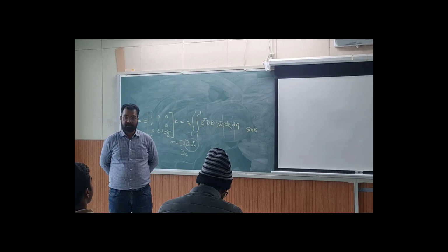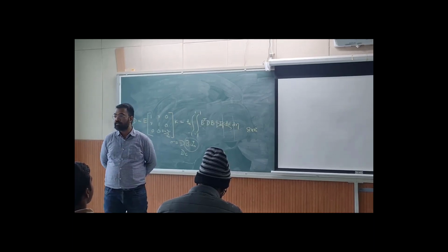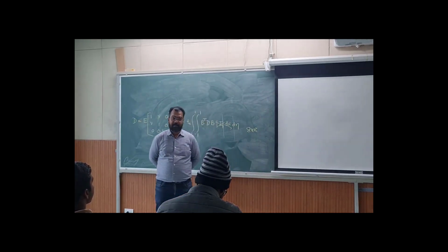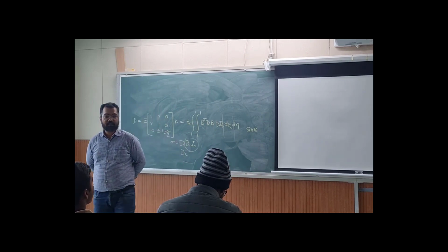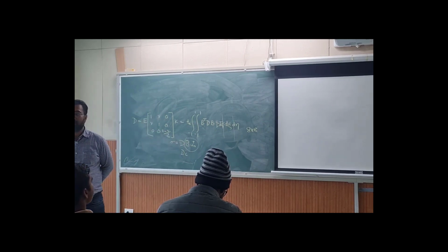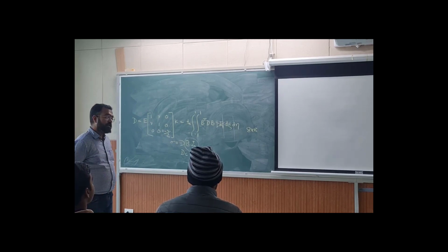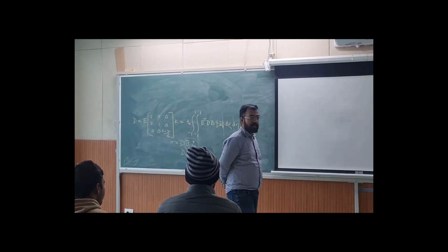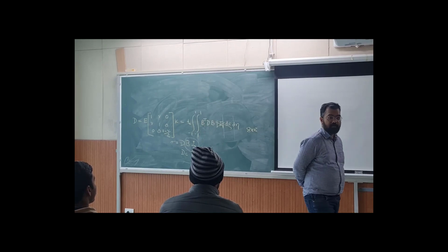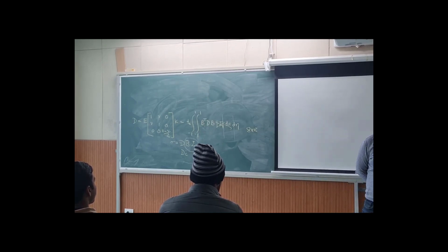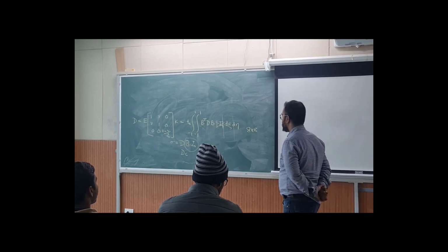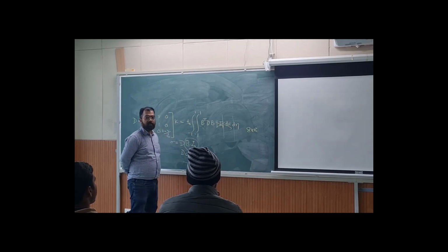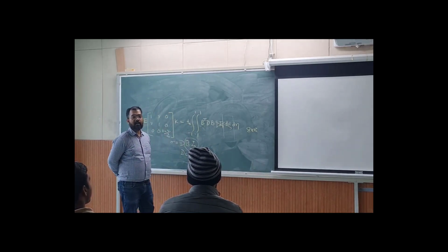Yes. You don't need to do this for this course. Yes, you are getting 8 cross 8 because there are 8 degrees of freedom. Right? So you have U1, V1, U2, V2, U3, V3. So now you should understand that whatever number of values you have in the column matrix of displacement, that into that will be the order of the stiffness matrix.